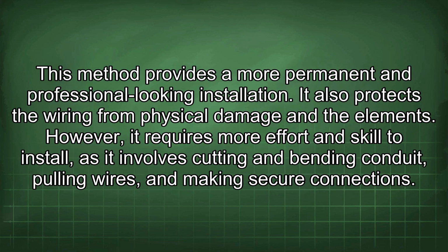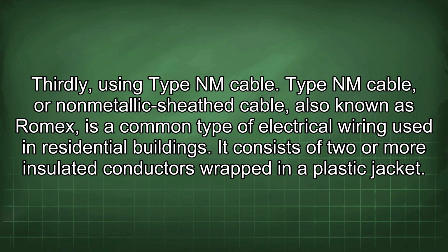This method provides a more permanent and professional-looking installation. It also protects the wiring from physical damage and the elements. However, it requires more effort and skill to install, as it involves cutting and bending conduit, pulling wires, and making secure connections. Thirdly, using Type NM cable.